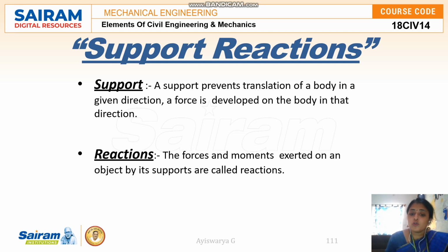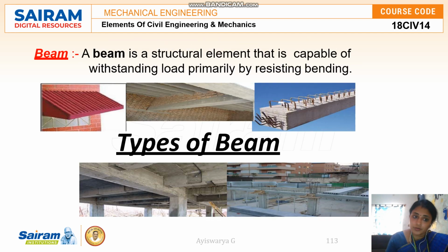Reaction means the forces and moments exerted by the object on the supports are called reactions. So wherever the loads are given and transmitted to the land surface, at that particular point there are some imaginary forces, or forces and moments, exerted by that support, called a reaction. So wherever you find a support, there you will find a reaction. So that is called support reaction, right?